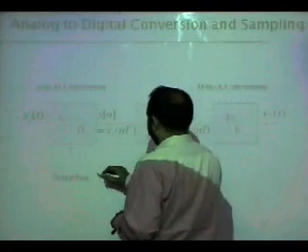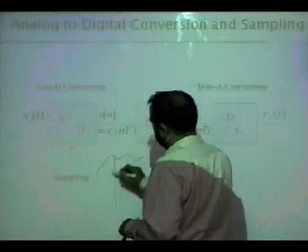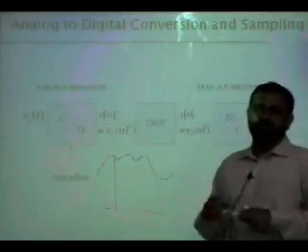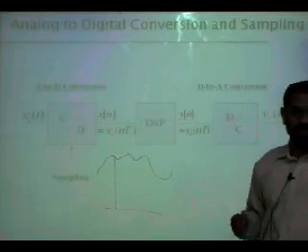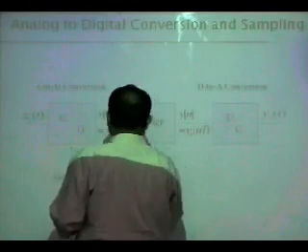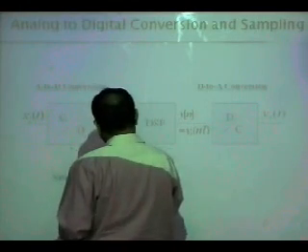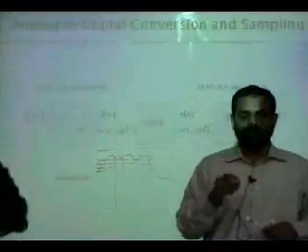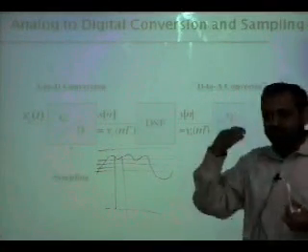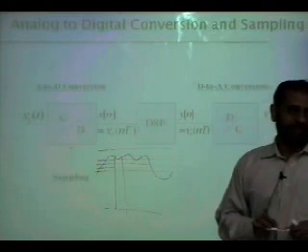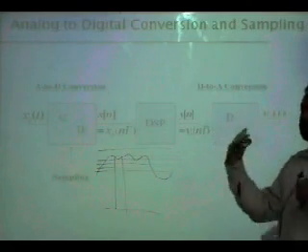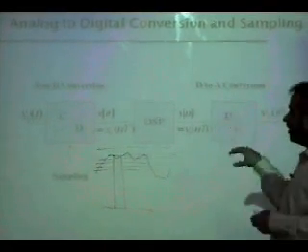Assume that if this is a signal, then you can precisely record the value of the signal, which is obviously not possible. That requires infinite precision. You have to have a finite number of levels, and then it may happen that once you sample, your sample does not appear on any one of the levels. It is between two levels. So this is called quantization. Then you have to quantize. Either you say it is the lower value or the upper value. This is a quantization noise which is fed into the system.